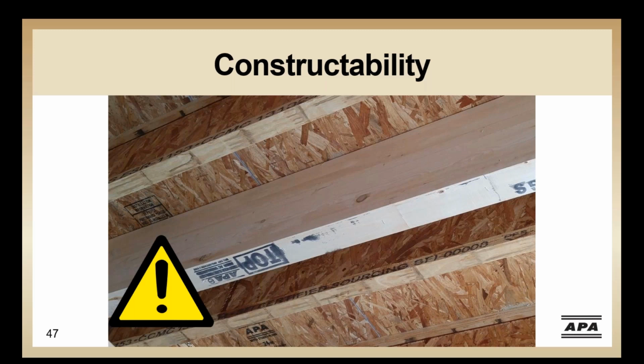Keep in mind that in addition to the unbalanced beam we discussed, camber beams also have a top and bottom. So you need to look at this. An unbalanced beam does have a capacity that can be checked. It loses about 25% to 30% of its moment capacity, and it has the ability to be reinforced if needed. Whereas a cambered beam will already be deflecting downward and is much more difficult to correct.